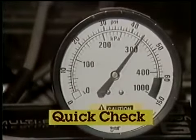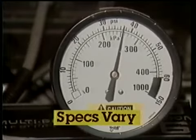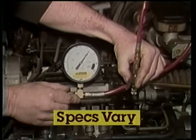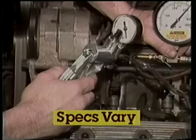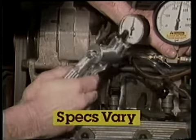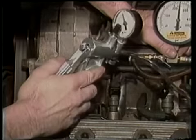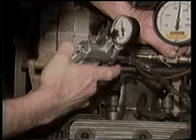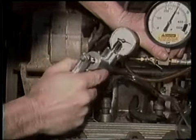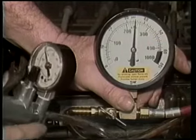The service manual will give exact pressure values for specific vacuum levels. If the unit is questionable, measure fuel pressure while using a vacuum gauge pump to check source vacuum at the regulator. The pressure gauge should read a specific level with a specific amount of vacuum applied. If pressure is not correct, other tests are needed to isolate the trouble.